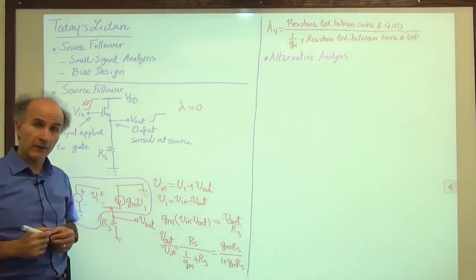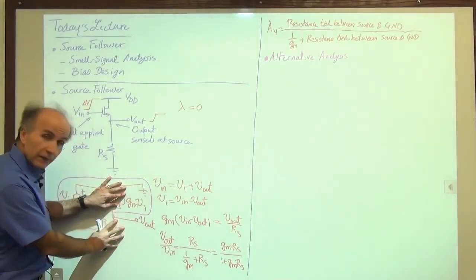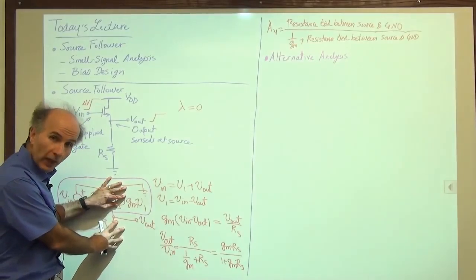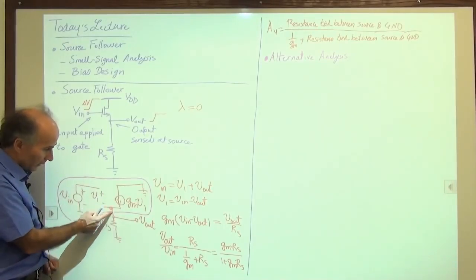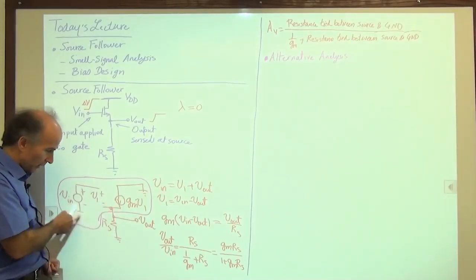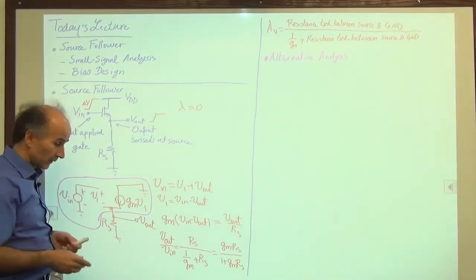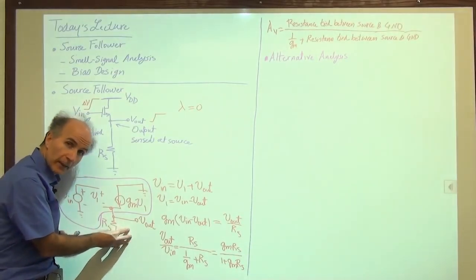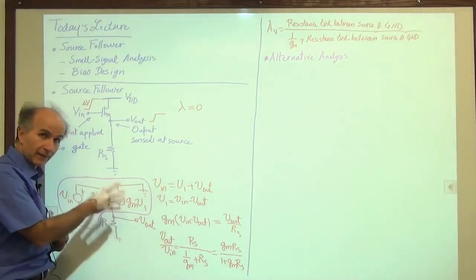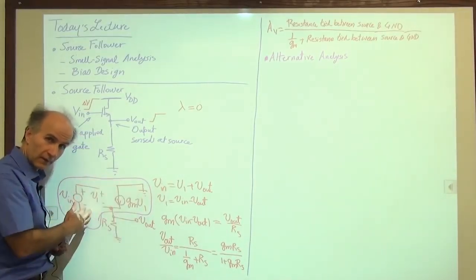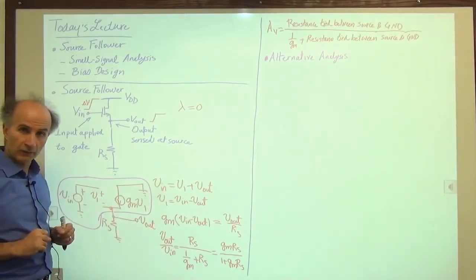All right, now you know that the Thevenin equivalent is possible only if this part of a circuit and this part of a circuit are connected by exactly 2 wires, no more, no fewer. So you can see that this circuit and this circuit are connected by this wire here and this wire here. This ground goes to these grounds. There's nothing else. You cannot have, for example, a dependent source here which depends on some value inside this box, or vice versa. That does not allow us to write a Thevenin equivalent like this. But here the situation is very simple. I just have this box, and I would like to find its Thevenin equivalent.